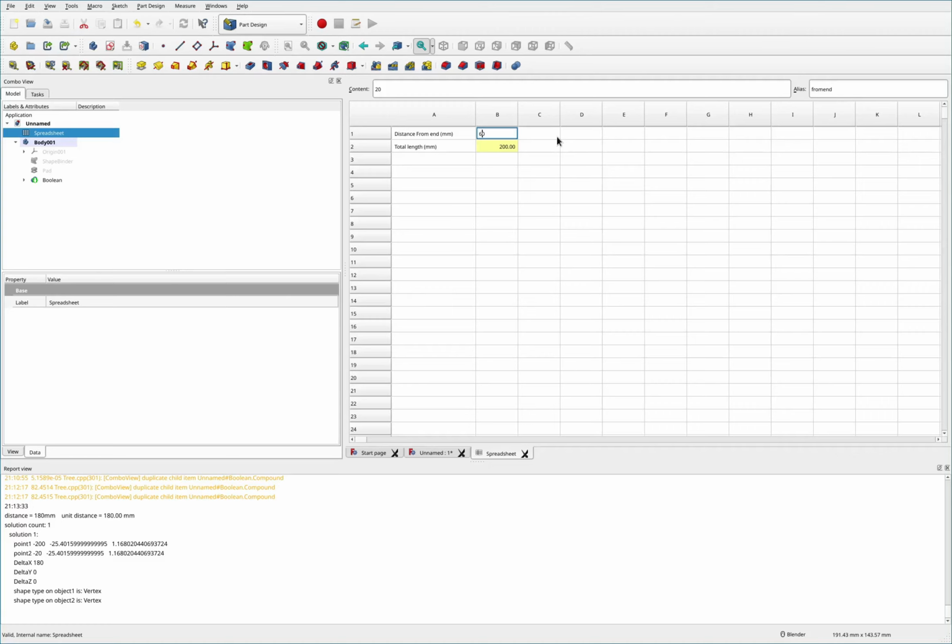And the good thing about doing it this way, as opposed to some of the other ways, is this should maintain the part naming as long as you're not using a version of FreeCAD with the topological naming problem.